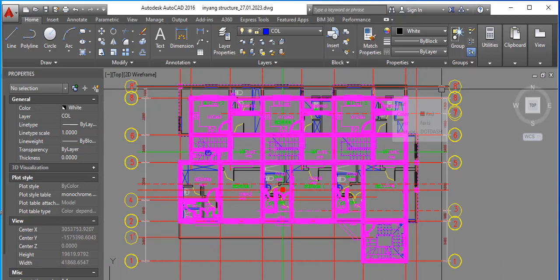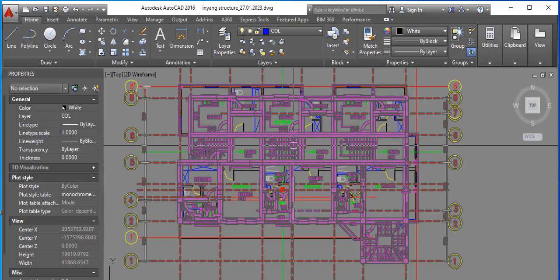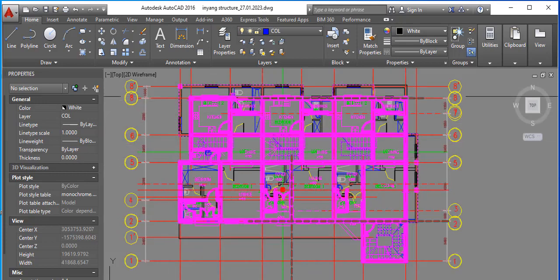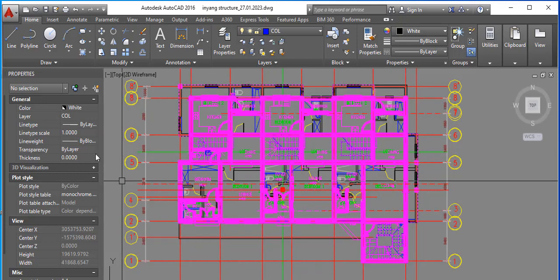So when you arrange your beams, pay attention. You know you are having cantilever, and there are two ways of having cantilever. Either you do a slab cantilever, or you push out your beams to pick the cantilever slab that is coming on the first floor over your ground floor. With this, you can now arrange your beams. This is how your beams will look, and now you know where your cantilevers would be.